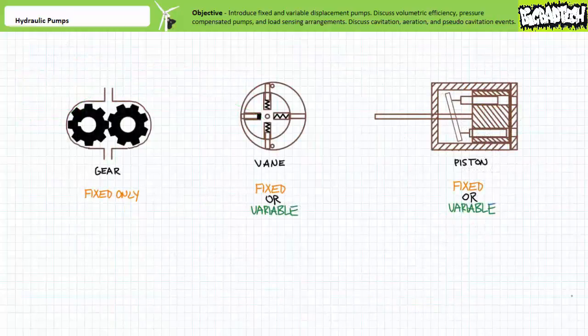Returning to much lighter subject material, 3 types of positive displacement pumps are commonly employed in hydraulic systems: gear pumps, vane pumps, and piston pumps. Pumps, regardless of their type, can be classified as fixed or variable displacement pumps. A fixed displacement pump, as the name implies, is incapable of varying displacement per revolution. A variable displacement pump, in contrast, uses movable internal components to selectively increase or decrease displacement per revolution as required.